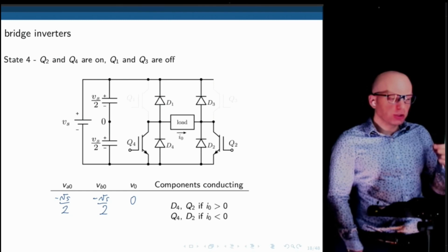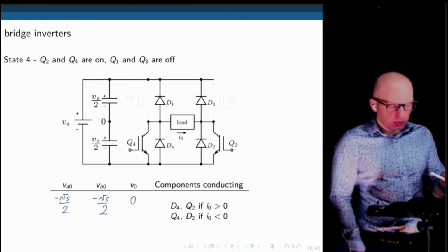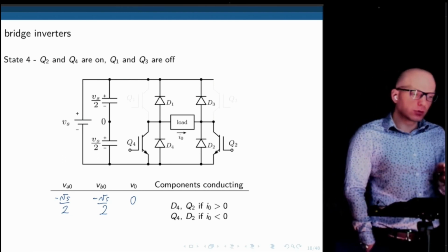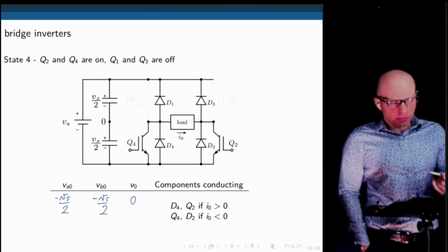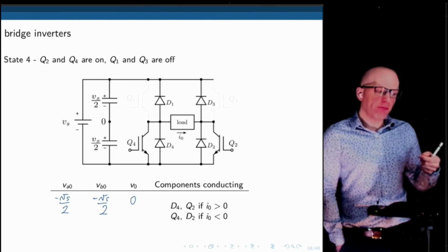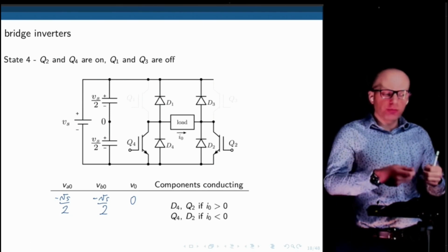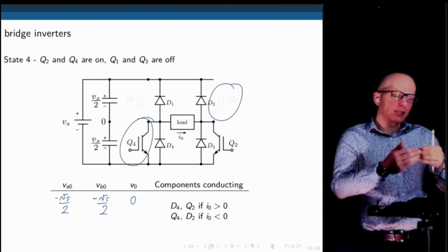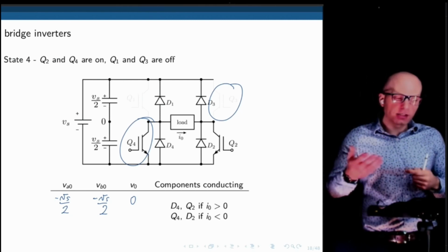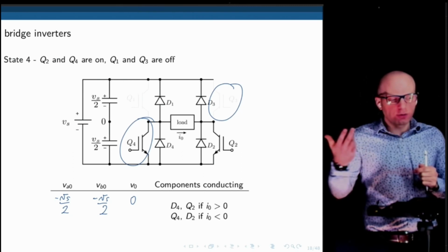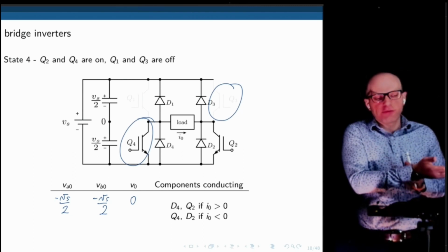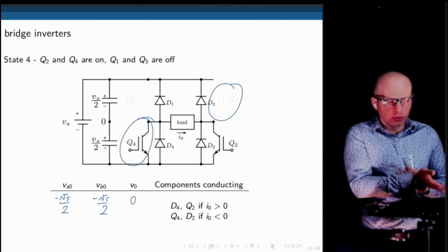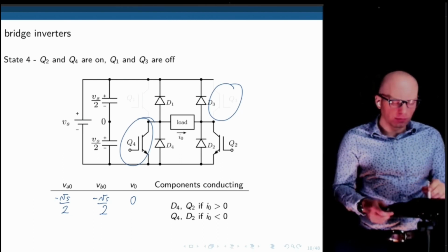Especially in low power mechatronic systems, you need to choose an H bridge that has a low voltage drop, and that needs to be taken into account. You may have used this before as an H bridge and concluded that it didn't have enough power in the output when you used, let's say, a 9-volt battery or a 5-volt battery. That is exactly due to the phenomenon that you mentioned. These two transistors were conducting. Each has a voltage drop that depends on the H bridge you're using, and they're taking voltage from the power input. So let's say with a 5-volt power supply, you end up with 3 volts actually being delivered to the load. So it is recommended to take that into account when designing this as well.